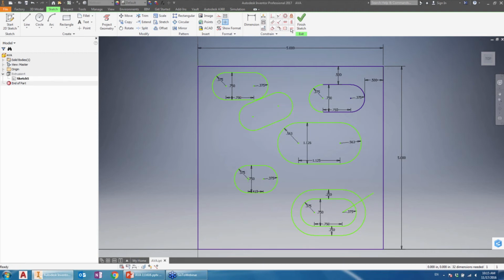And the last 2 tools that we have in here are the trim and extend. They very much go hand in hand, but these are probably the 2 more commonly used ones that I use. Basically, extend will extend any geometry to the next geometry. It won't extend until you actually click, but it will give you a preview. So if I hover over this line, it will show you where it will extend to, and so on and so forth. It'll also do arcs, so if you keep going, I'll make a complete circle eventually.